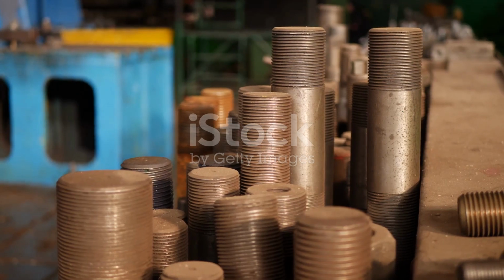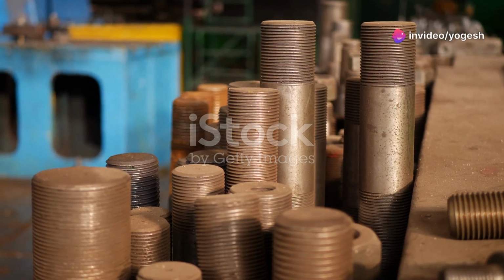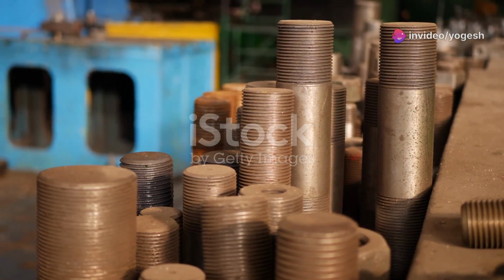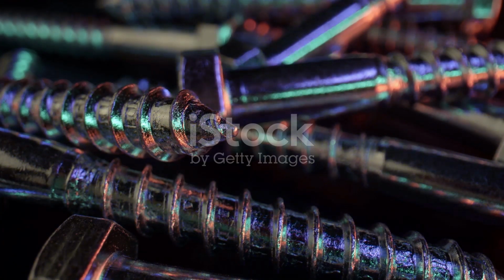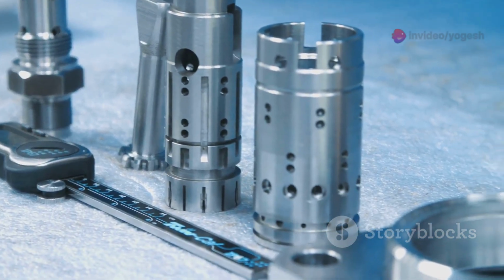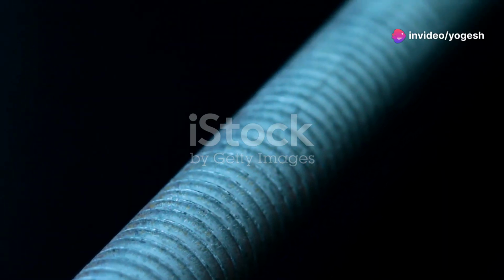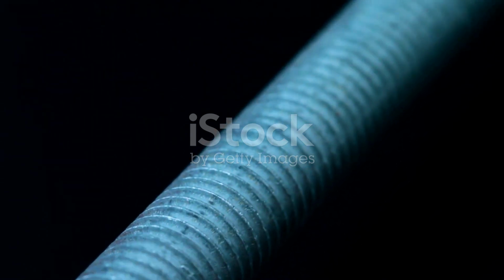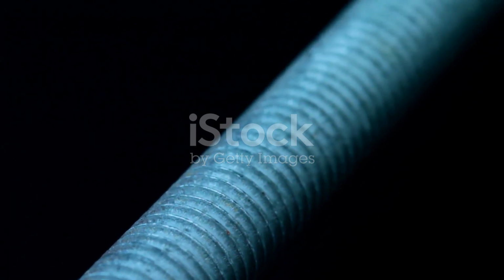Unified threads, commonly used in the United States, are designated by the inch symbol followed by the number of threads per inch in the thread series. This system is different from the metric system, but serves the same purpose of providing detailed information about the thread. For example, 1/4-20 UNC represents a unified national coarse thread with a diameter of 1/4 inch and 20 threads per inch. This notation helps in identifying the thread type and its specific characteristics, ensuring that the correct thread is used